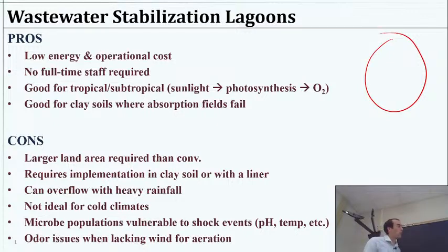It's not a great option for cold climates. These lagoons don't work super well when they freeze over. Bacteria don't like to grow too much. It's still possible to an extent, but you have to add some extra capacity, plan for how much is going to just be stored there, and plan for the time when it starts being released, and how you can make sure that's going to be sufficiently treated, and all of that. Just all of those considerations, it's just not so ideal, even if possible.